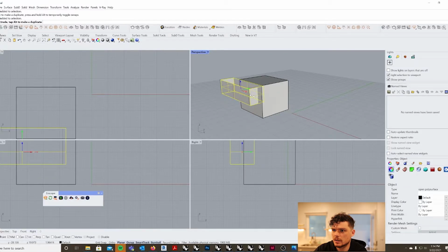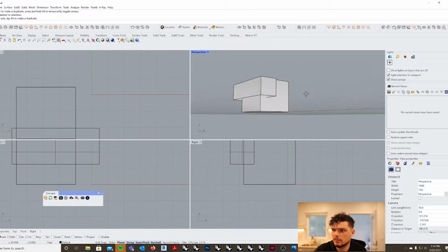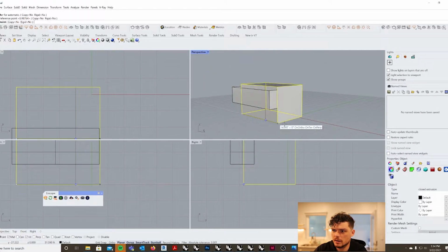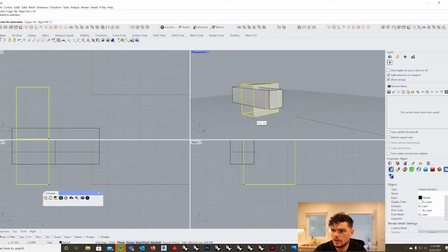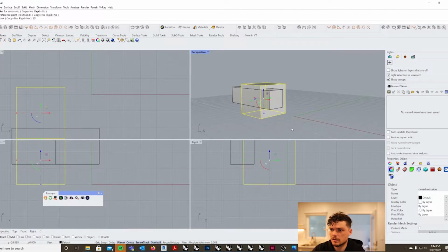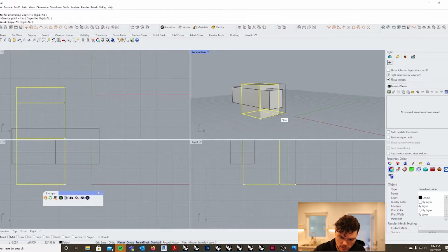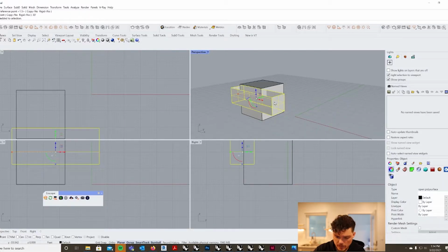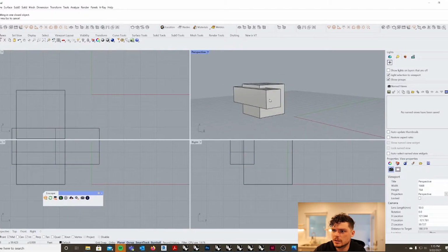And then this is just going to be off of our main volume here. And then we can make this, I don't know, 20 feet, and have this, well, let's make it 30 feet. So I'm just hitting scale 1D, and then I'm going to type in 30 feet. And then let's just make it 30 feet in that direction, and I'm going to go ahead and cap this.